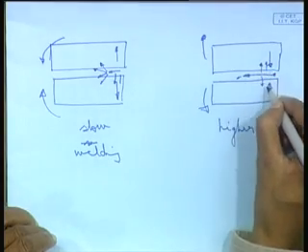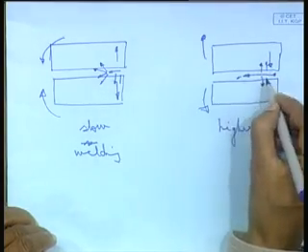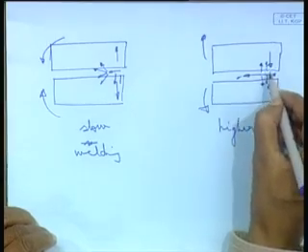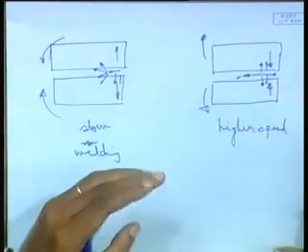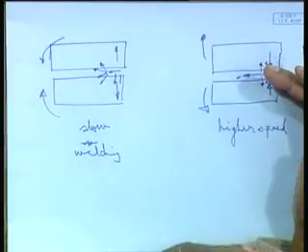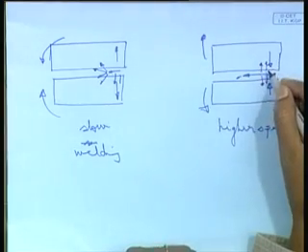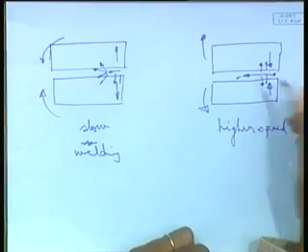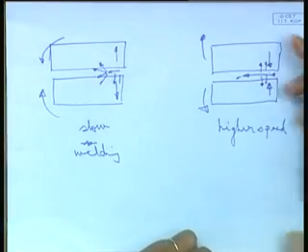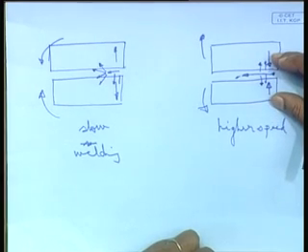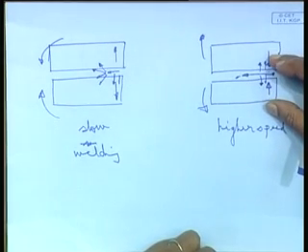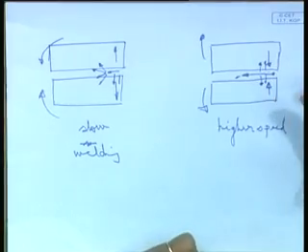But if the speed is significantly high, then what happens? Whatever heat is flowing, heat dissipation, that will be transverse. Transverse means more shrinkage forces at the back. So, it will tend to close in a higher speed welding, more shrinkage forces at the back of the weld, at the trailing edge of the weld.